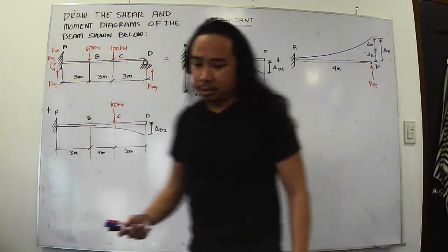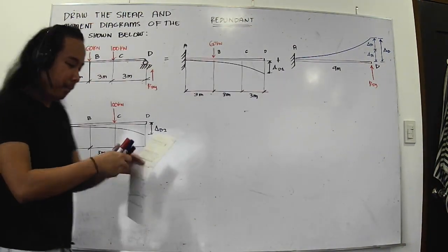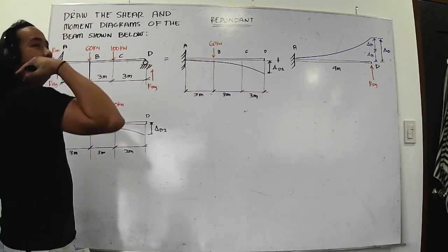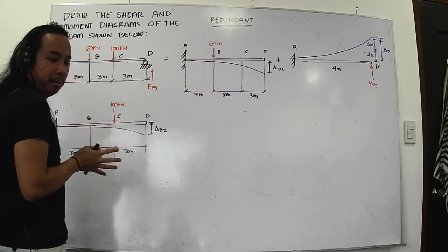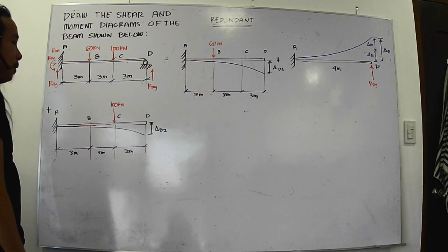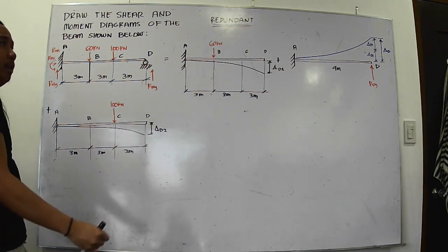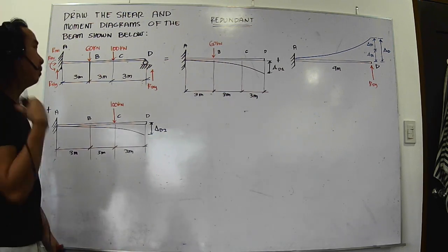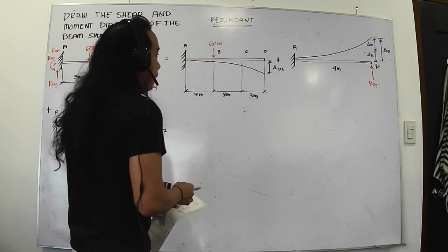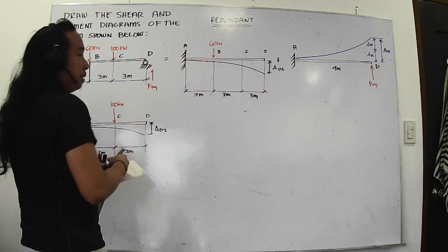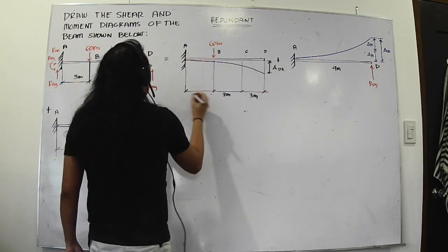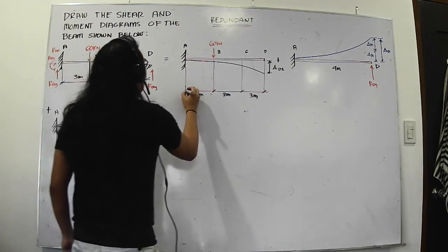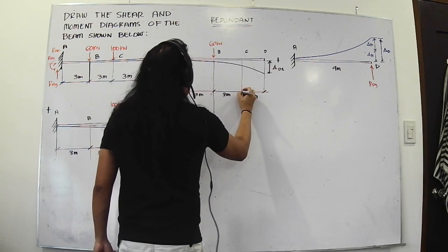Before we could add deflections, we need to solve for those deflections, right? You can use any tactic you want. I've already taught you the classical techniques on how to solve for deflections, from your midterm topics. We have Castigliano's theorem, energy methods, geometric methods, and the direct integration of the elastic curve equation. Now, I want to use the conjugate beam method, also for delta D1.